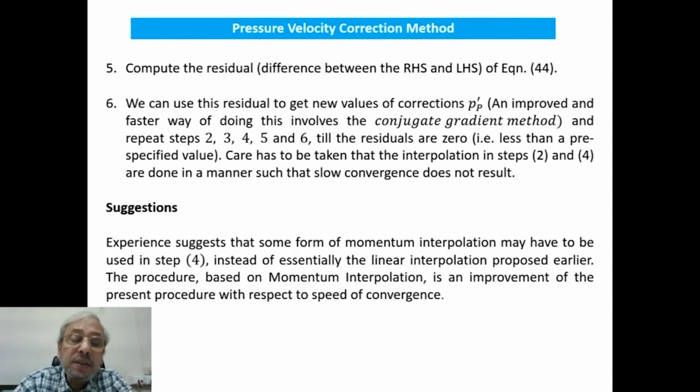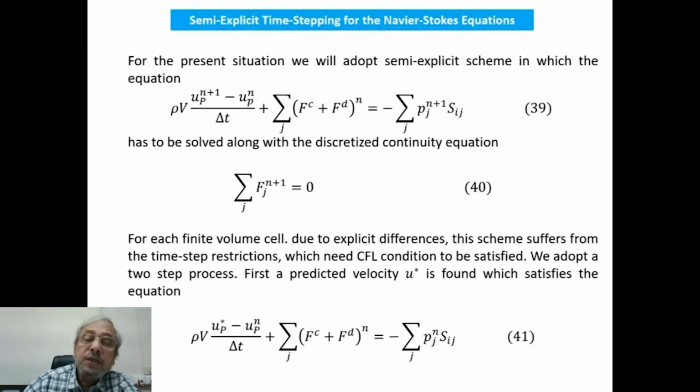The procedure based on momentum interpolation is an improvement of the present procedure with respect to speed of convergence. So in this process, calculation of diffusion flux, convection flux, and the contribution from the pressure are different from what we discussed for the MAC and SIMPLE algorithms.